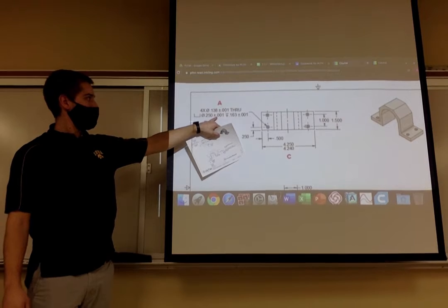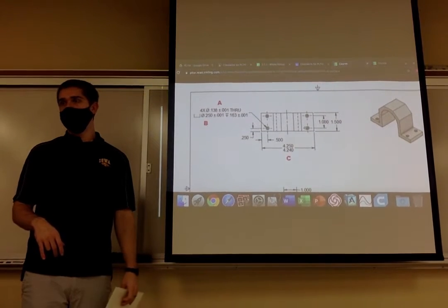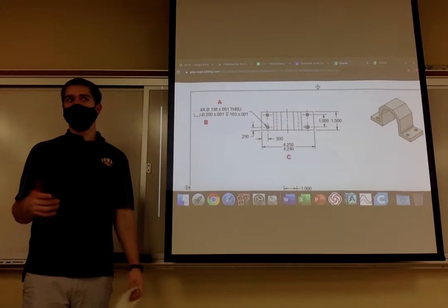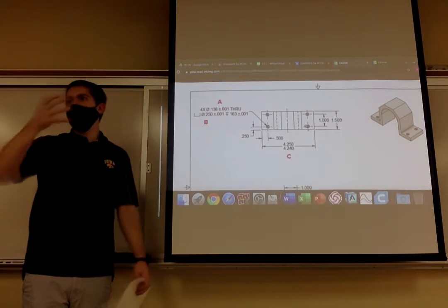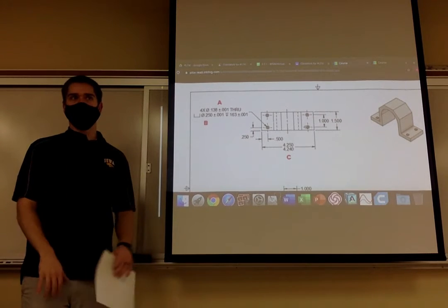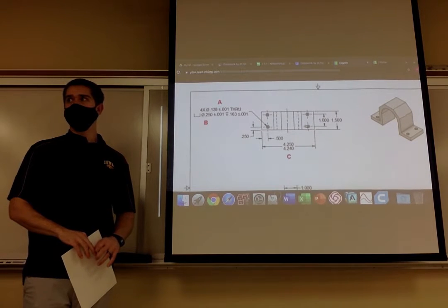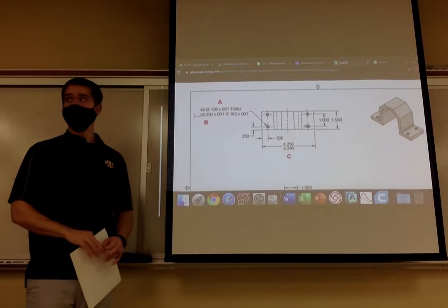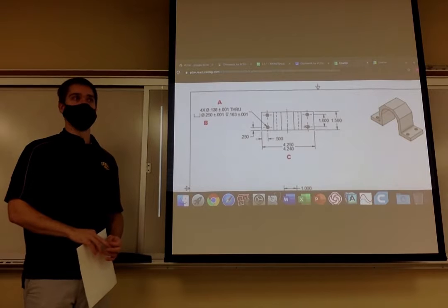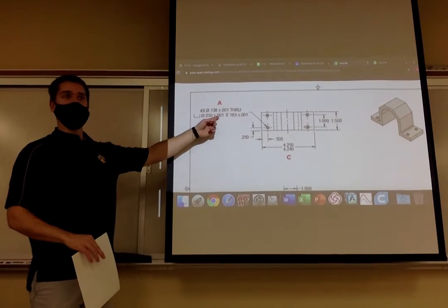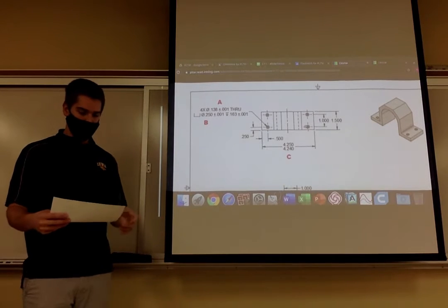Good. B, 0.25 inch diameter hole, plus or minus 0.001. What type of tolerance? Bilateral. Same thing. I give you two directions to make an error, basically. What's the total tolerance? Correct. 0.002. If I give you error in two directions, I need to add up both of those to say, hey, you have a total room for error of 0.002.